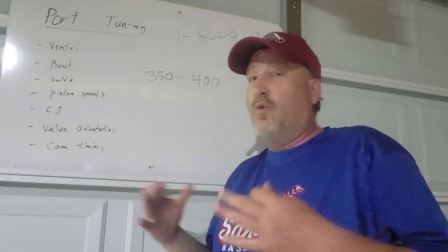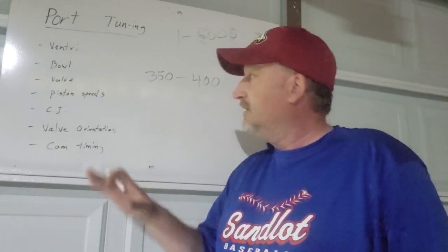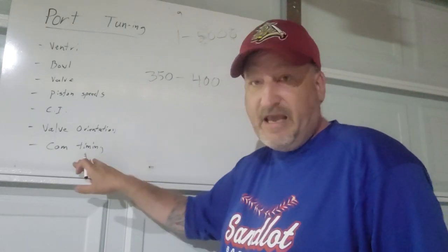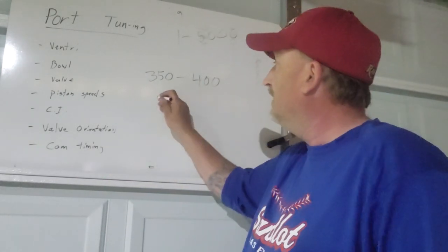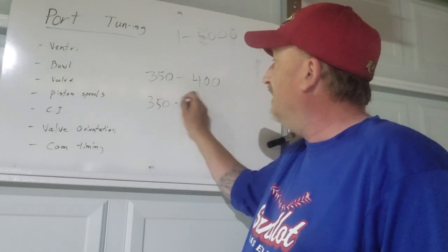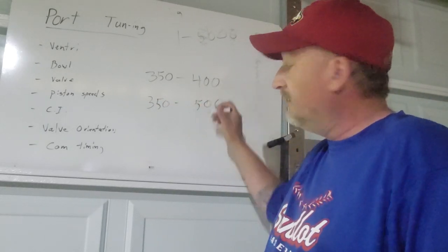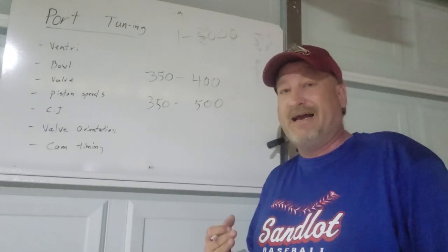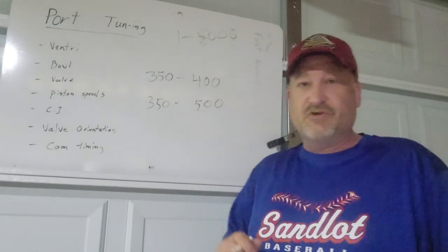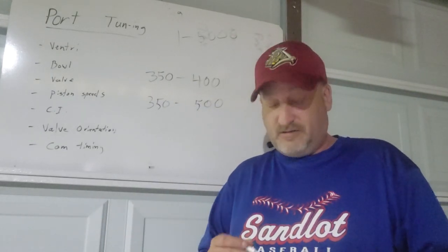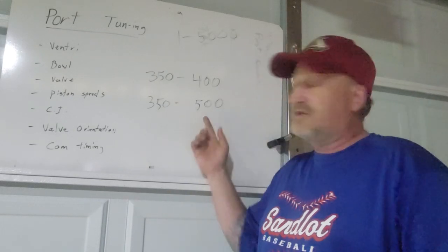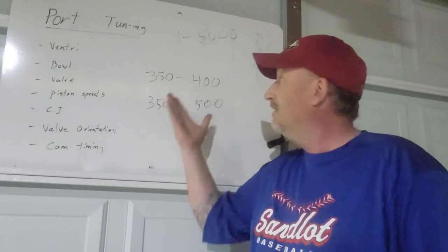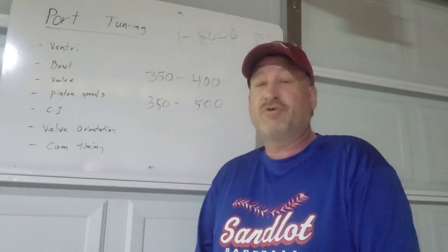If the customer was all worried about dyno numbers, without changing anything at all within the 350 except for the cam, going to a larger cam, I could create a 350 that made 500 horsepower, which looked really good on the schematics from the dyno. But as soon as the engine was dropped into a car or vehicle of the customer, it was a complete dog. They're happy with the numbers and the paperwork from the dyno, but it was junk on the street.